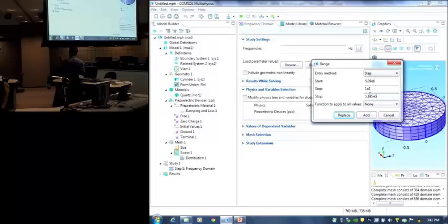Once you get the eigenfrequency, then you would like to sweep in and around that eigenfrequency. So I first did an eigenfrequency simulation, and then I got the eigenfrequency, and then I'm sweeping around that eigenfrequency, and that's how I got these numbers. What about the stepping of the frequency? That's also something you have to be careful about.